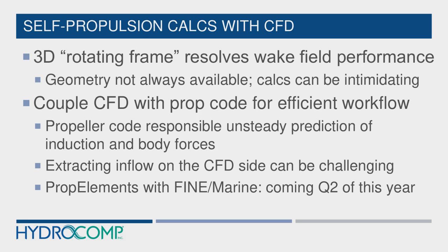One caveat is extracting the inflow on the CFD side can be a bit of a challenge. Where do you put that inflow plane? It can't be at the propeller. It's always a little bit upstream, but how far upstream? Are there corrections needed? Is that inflow plane intersecting a piece of stern structure that's going to disrupt what's really going on at the propeller? So there's a little bit of skill in setting that up as well.